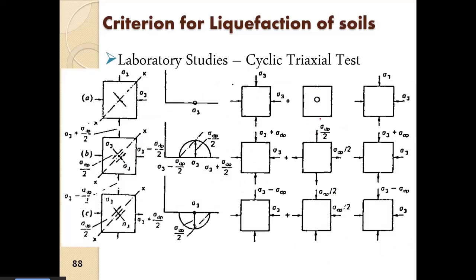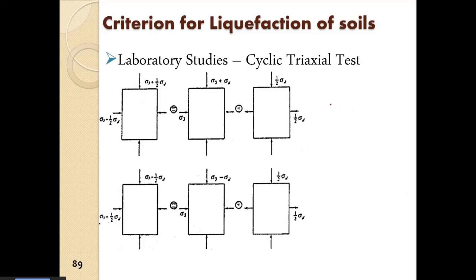Whatever increase in the total cell confinement happened, the same amount of increment happened in the pore water pressure, and therefore that aided in stabilizing the effective confinement at the same point. So the Mohr circle only grew in radius, with constant mean and extreme principal stresses, then again it will shrink back. So the pore pressure aided in taking that into consideration.